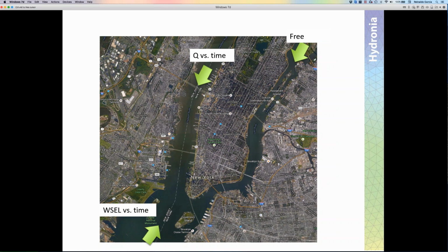So it's automatically accounted for in the model whether this is an inflow or an outflow boundary as a function of the water elevation time history that you provide there. So this water elevation versus time can be any water elevation. It can be a tsunami, a tidal record, a storm surge, any variation of water elevation versus time that you need to create a scenario for flooding in this area.